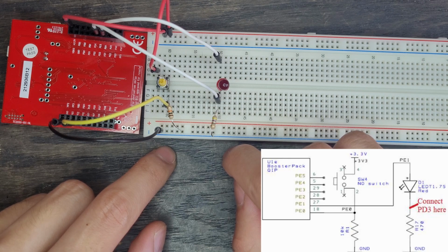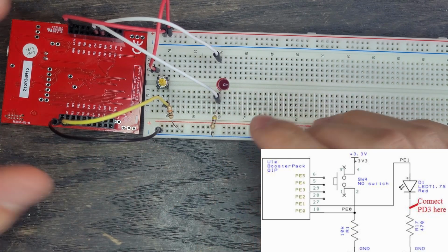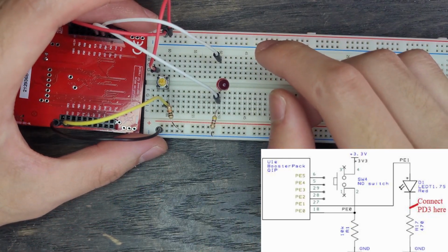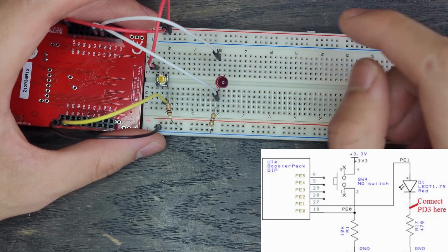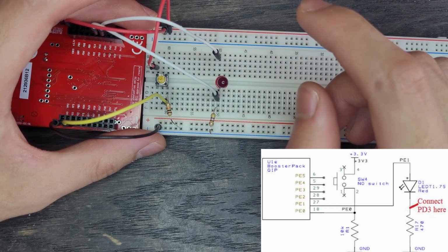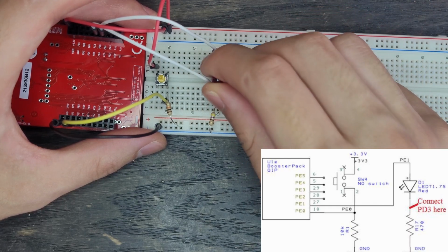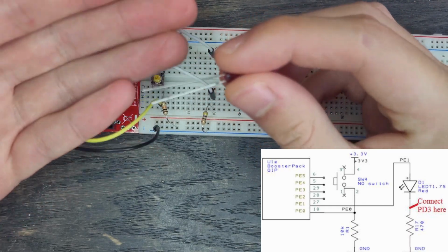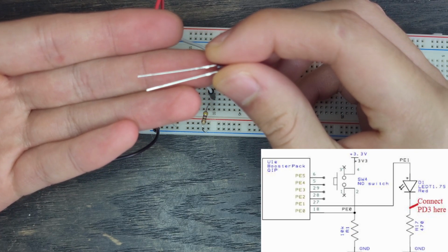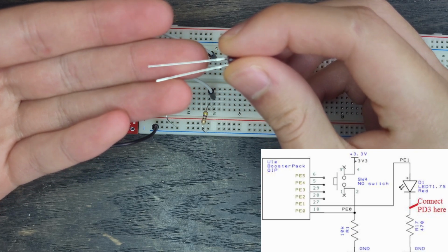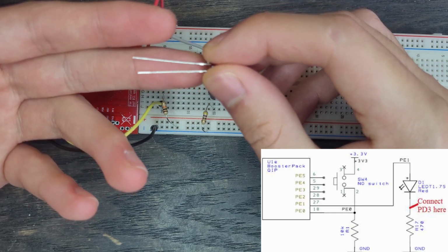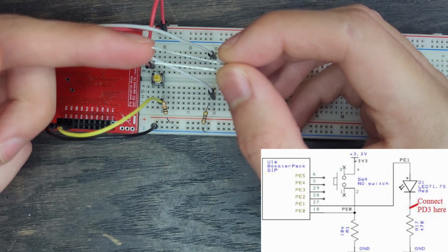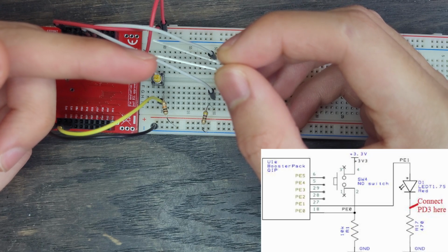So what else is next? Well, if we keep going up from here, the next thing is our LED. Now remember, in the circuit diagram, the plus is on the top, so that means it's the anode. It's where the current flows into. So when we look at this LED, we're going to want the longer side to be on the top part. I kind of like to build my breadboard with the circuit diagram, that way we can really see what's going on. So we have the anode, we have the cathode right here.